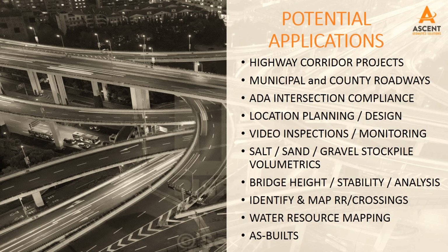Yep, that's right. So the last couple things we'll mention are volumetrics. Obviously that's an easy one. That's a no-brainer with UAVs. As opposed to having somebody climbing up with a rod on these huge stockpiles, that doesn't make sense today when you can easily just have a drone go up there and collect the data in a tenth of the time, and you're collecting it probably to within better accuracies than crawling up that thing.